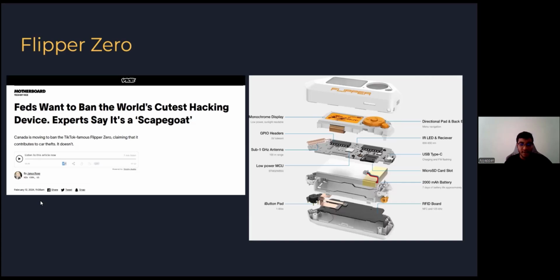You'd mentioned certain frequencies, so by default, the Flipper, because of FCC regulation and other things, you're not allowed to actually transmit on certain frequencies. So by using unofficial or open source firmwares like that, you can transmit on certain restricted frequencies. You can use this as a jammer for anything under 1 gigahertz as well, which is fun. But you also have to be really responsible because some of the medical devices also operate on the same frequencies, so you might hurt someone in the process of doing so.